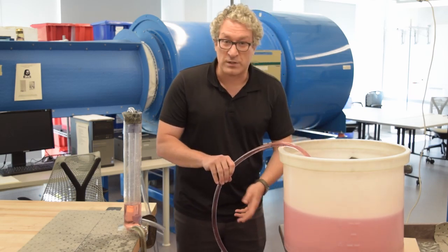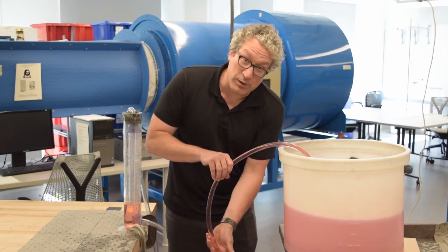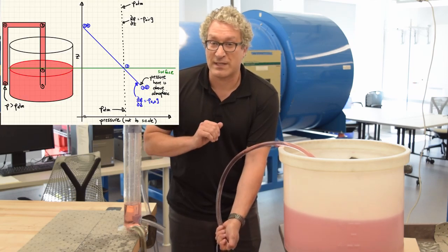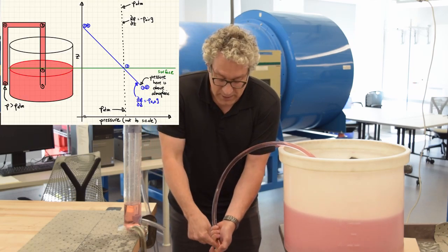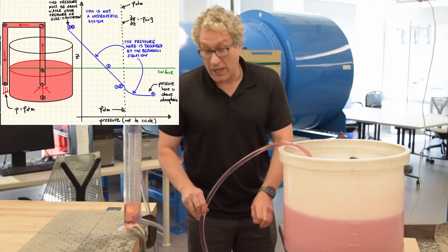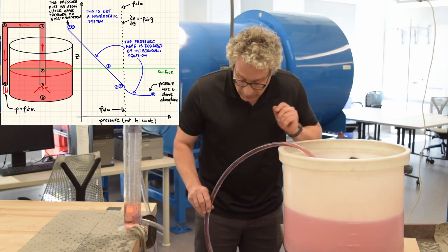In fact, as soon as the fluid is moving, all of our hydrostatic equation arguments are not complete, and they can't be used to describe the system. If I hold the system fixed with my thumb, the system's static, and the hydrostatic equation applies, it tells me that this pressure must be higher. As soon as I let it start moving, now I have to use the Bernoulli equation to describe how this fluid moves, and that's the topic of the video.